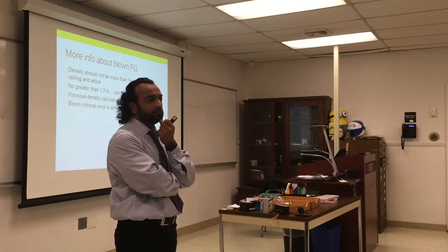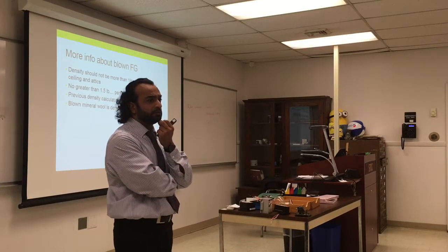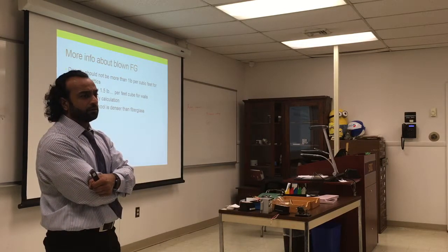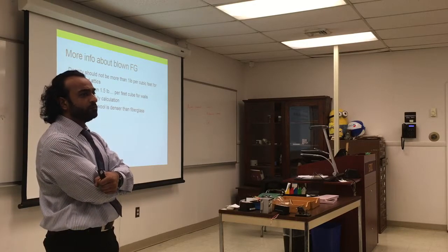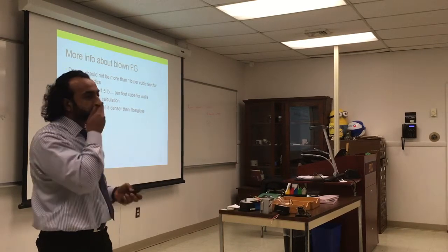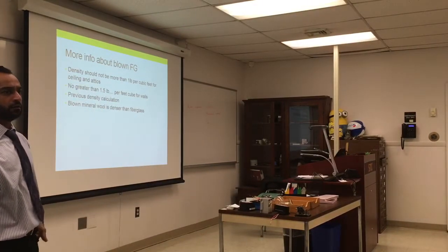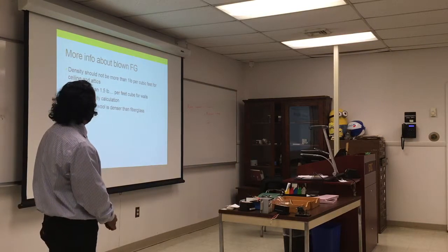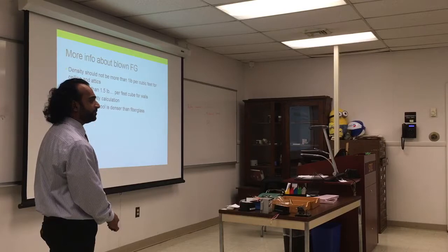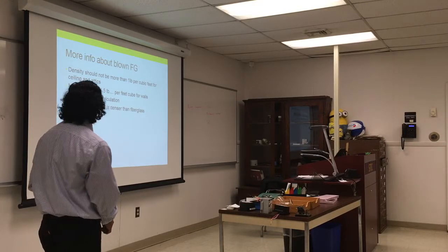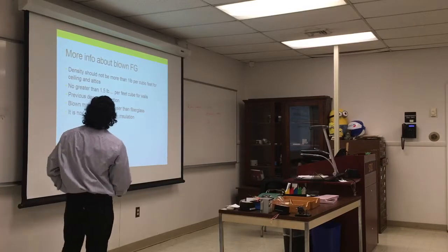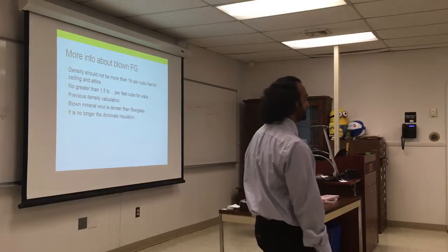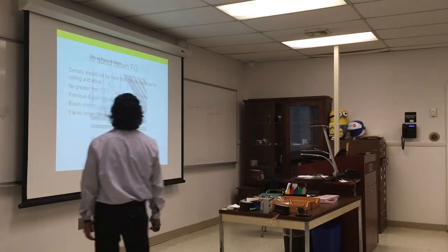And I knew the outside insulation was hydrophobic, so it would wick the water away from the walls. I knew the whole point of this house was to be green and energy efficient. You can also use fiberglass with mineral wool. Mineral wool was very common in the 80s, but it's not very common now. But there are other options. It's no longer a dominant insulation, but it was very common at some point. They found better things that are easier to install and with better R value.